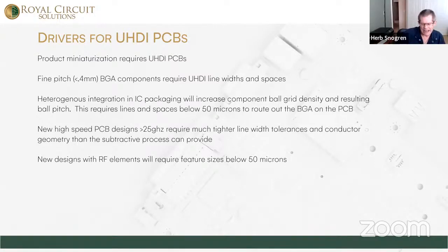So a chip scale package is typically done with wafer level packaging. And so the actual package size is the same size as the die. Through wafer level packaging, they add dielectric layers and circuit layers onto the wafer. And then they terminate out to their bump or the ball, and then they cut that out of the wafer.